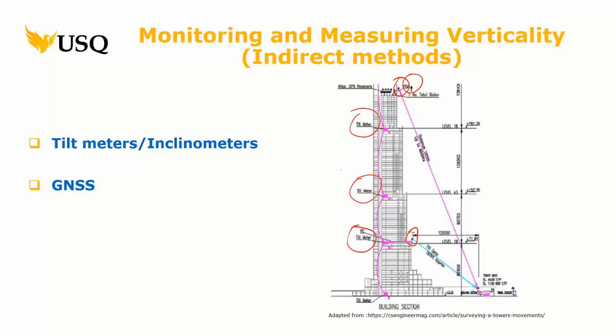So that's why locating them critically, they've got to be in critical points. You want the tilt meter to give you data. So in this particular case, these points would have been worked out with structural engineers, probably in consultation with surveyors, right? So as the building got constructed, there's actually measurement of these tilts continuously. Then there'll be, right back to the very beginning, the structural health, which has to go on forever, right? Those same tilt meters will be used for that.